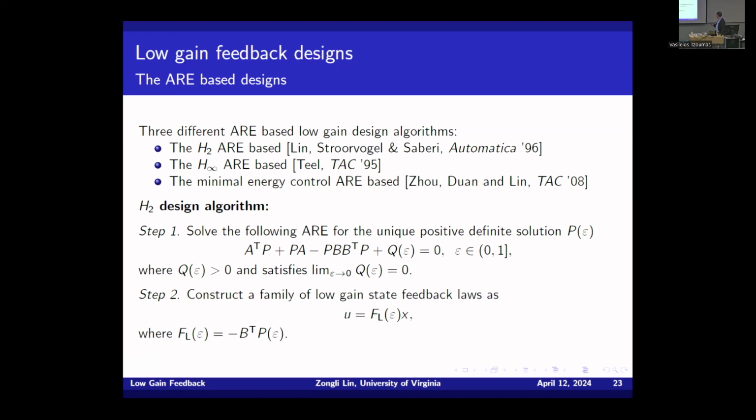And more recently, I had a student in China, and we worked together and came up with a minimal energy based control. And this one is nice in the sense that I can set the Q matrix equal to 0. That way, the Riccati equation will be reduced into a Lyapunov equation, and that way we can get the discrete solution. But the properties are all the same.